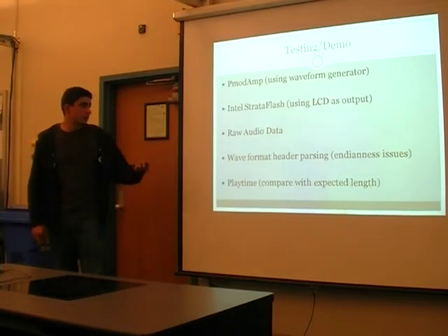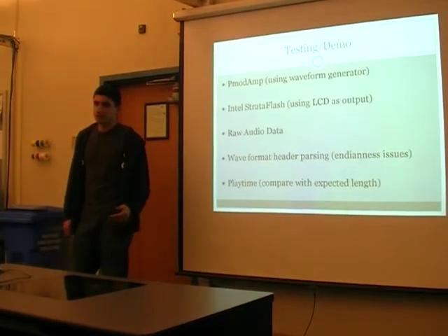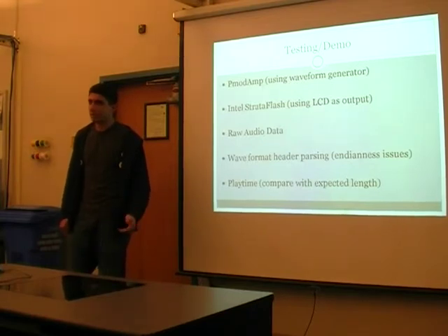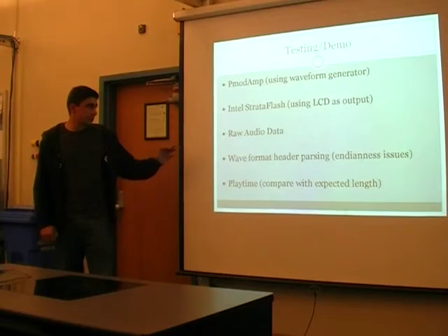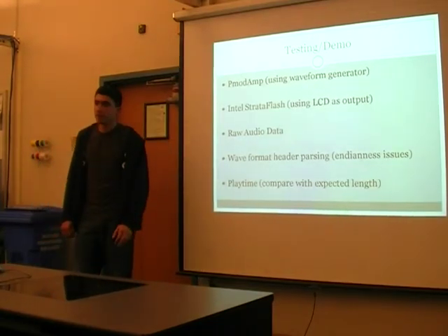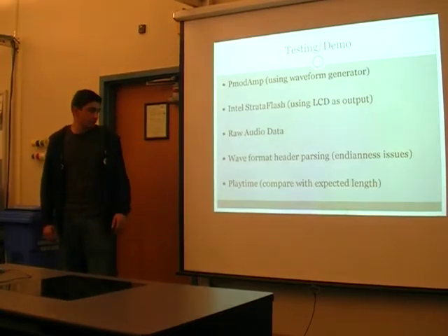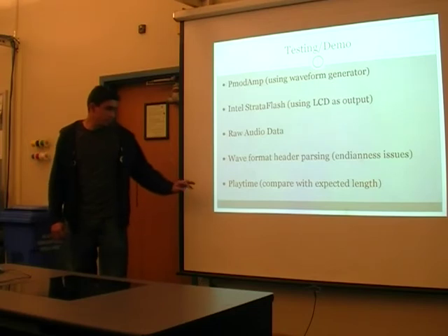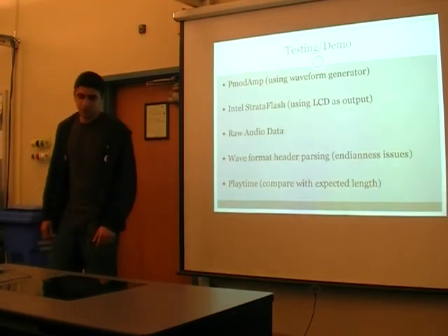Afterwards, I used raw audio data, which is just a WAV file without the header, and hard-coded the sample rate because I knew what I was putting on there. Once I got that to work, I decided to parse the WAV header so that I can use multiple sample rates. Then I tested the playtime by comparing it with the actual length of the song.